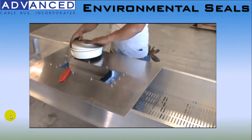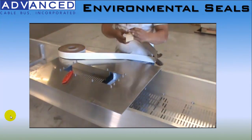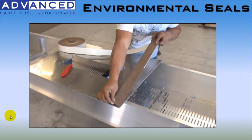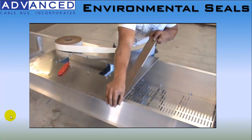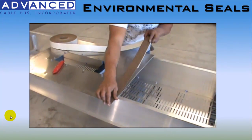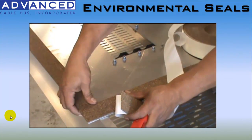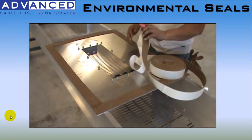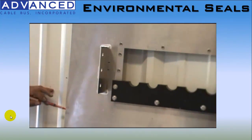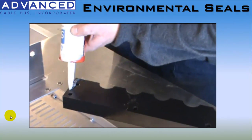The next step is to line the edges of the environmental seal plate with a rubberized cork tape that would allow your seal plate to achieve a successful sealing against the wall or the surface to which you're attaching the seal. And once you line the edge with a rubberized cork, you can bring the seal plate to the wall to mark out the opening, to mark out the cutting points, and to mark out all the bolts.